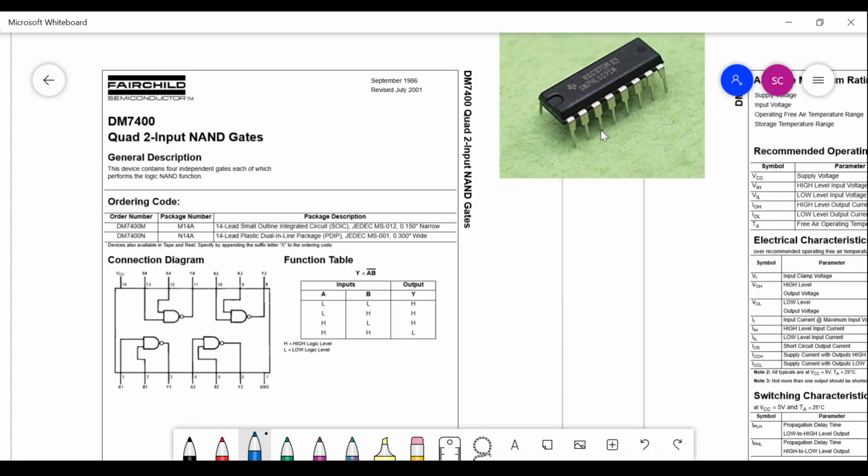Now you have a very physical thing with you, and if you want to do the NAND operation of two logical variables, 0 and 1, you would supply those variables to these two input pins, and the result of the operation you can extract from this output pin. You will see whether it is 0 or 1. In that mode you can perform an experiment to see whether the NAND operation is being performed by this NAND gate within this chip. It is a verification. This is one of the experiments that you will actually do.